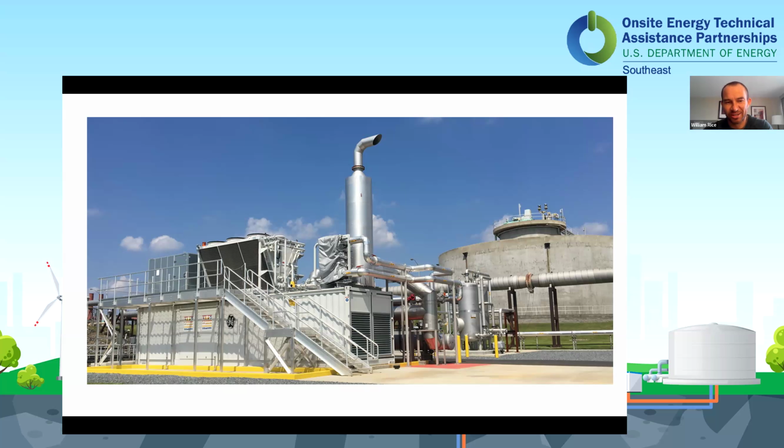It's a 20-cylinder engine. Some of the temperatures on the heads get to like 600 degrees C. Whenever I don't insulate the engine correctly, you can kind of see little pockets of bright glowing steel through some of the openings. It's really exciting and neat. And then of course that's just a big giant muffler on top there. It's pretty quiet.